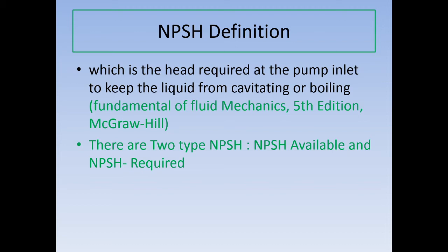So you have to translate that into your application in the field: based on the formula, the NPSH available in your field must be bigger by around 1.5 meters. This is according to the ISO as well. So it means your NPSH available on the field, or your design installation, should be 3 plus 1.5 meters.